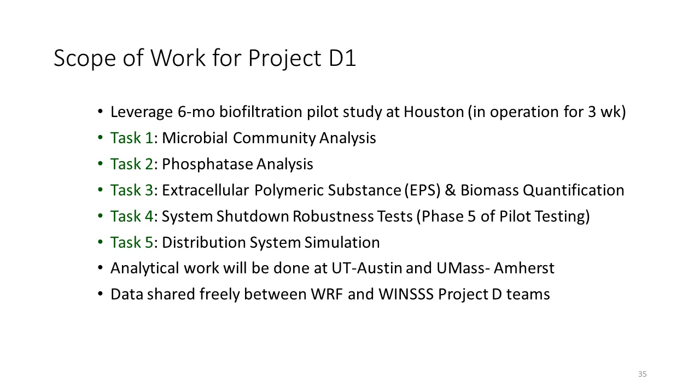EPS: when we talk about the hydraulics of a biofilter, it's the EPS, extracellular polymeric substances, that can really drive that, not so much the bacteria, but the sticky stuff, the biofilm. So there will be EPS and biomass quantification. And then there's a robustness testing phase of the piloting, where we've added some system shutdowns. You talked earlier about the fact that small systems are operating on and off, and that's what this is going to be. We're going to shut the system down, turn it back on, and see how it impacts performance as well as some of the other parameters we're tracking.